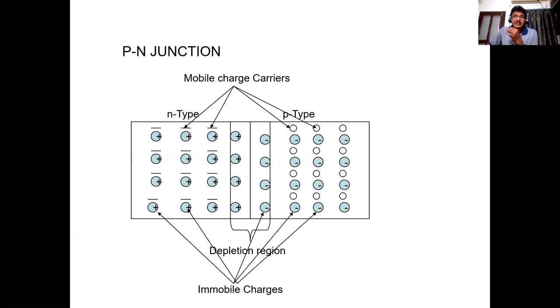That's why a semiconductor laser is not possible with only N-type or only P-type. It is a combination of N and P, so a semiconductor laser is a PN junction. But we need more excess carriers here, so we have to dope heavily. So a semiconductor laser is a heavily doped PN junction.